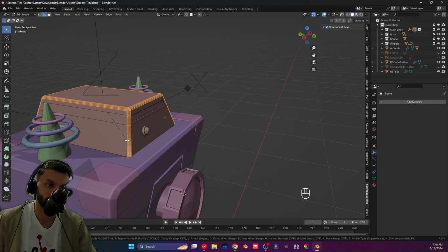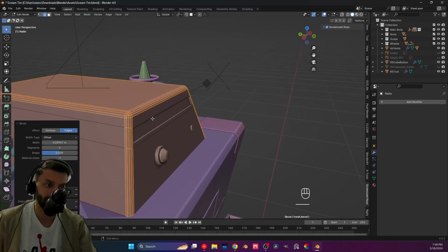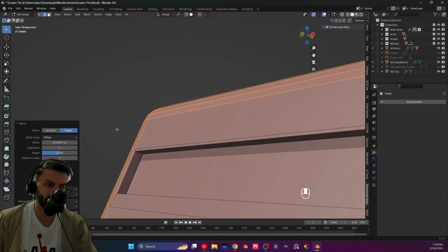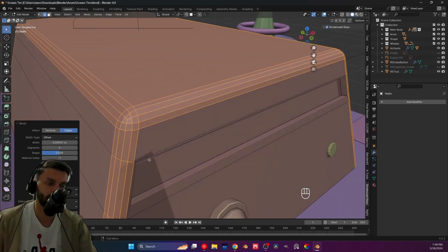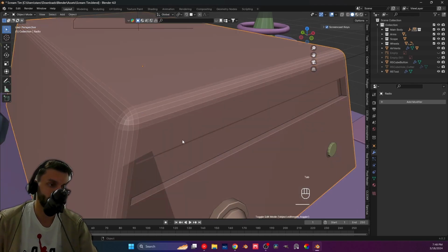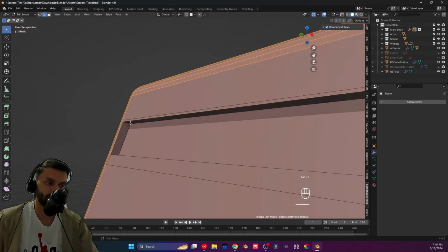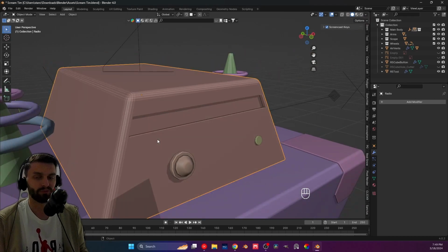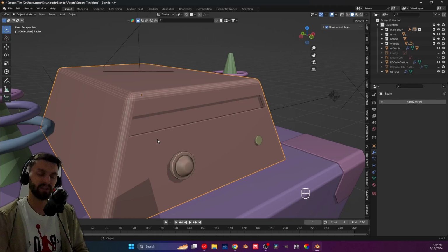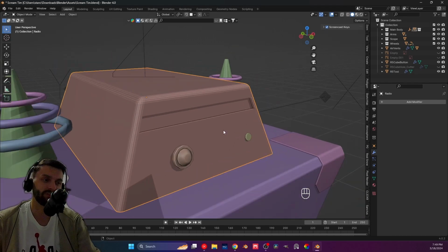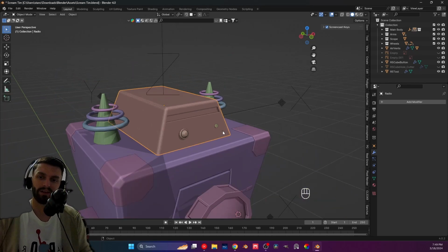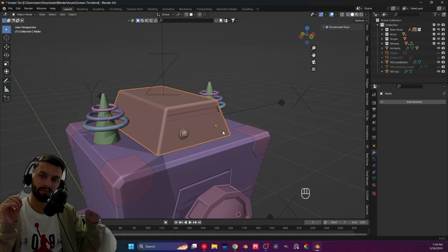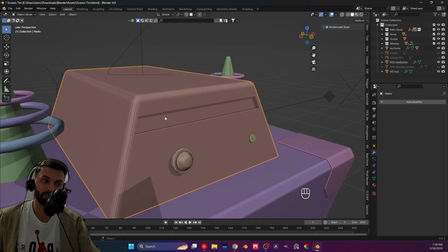So I can add a few more edges right here, and then even play around a little more from this menu, which does give me a little bit more freedom about it, right? So I can actually put 5 here, and now I'm pretty good. And of course, I can give a different bevel to this one. Now, yes, of course, that takes more time because this is manual work, but again, it does also help because round edges are not usually the same for exterior edges, like for this big body. Of course, the round edges are going to be bigger than it's going to be for the inside here.